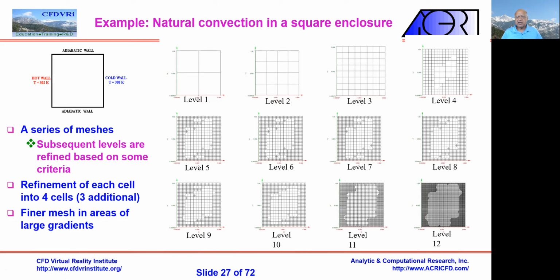So the computer then went to the next level, and since we didn't know the direction, we said isotropic. So go to the next level, and we have this. We can go to the next level, we have this, next level, this, and similarly. So you see what happened here. What happened is that it kept on refining automatically, and it kept on creating finer meshes in the area.